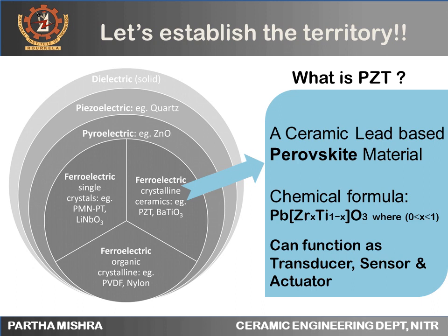And not only can we use these ferroelectrics to build better capacitors, but by utilizing two important aspects, the change in the crystal structure and the state of polarization, we can make better piezoelectric materials. So let's face it, what are piezoelectric materials, or what is piezoelectricity? Piezoelectricity is basically made up of two components: piezo, which means to press, which implies there is a mechanical motion in response to a force being applied to the material, and electricity, which is what the material is able to produce in response to the force applied. So these materials are able to generate electricity in response to a mechanical strain.